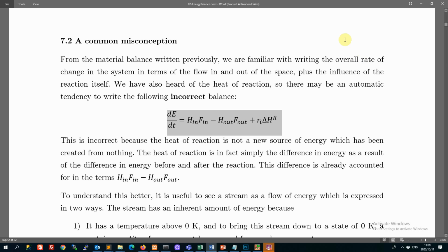But that's not what we are saying here. So here we are talking about one phase. So there's one temperature. So we need to account for each component as parts of the fluid. So we don't tend to write individual species for the energy side of it. Of course, that doesn't prevent us from, if we wanted to, writing the individual contribution from a component.